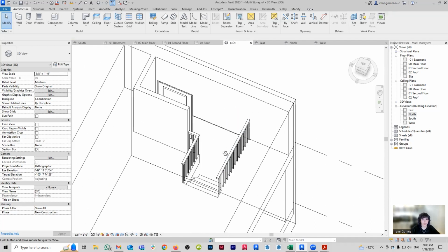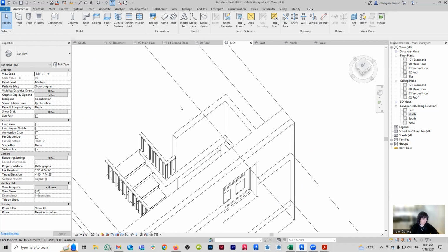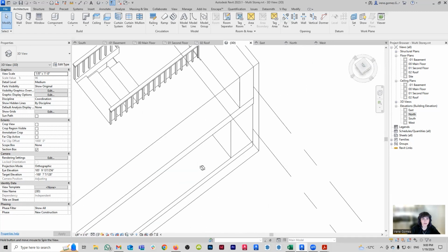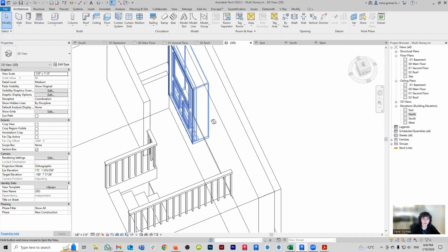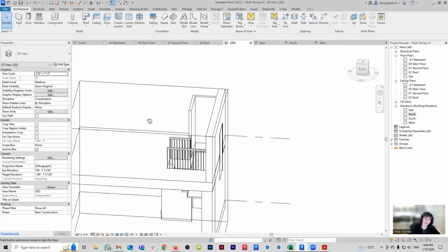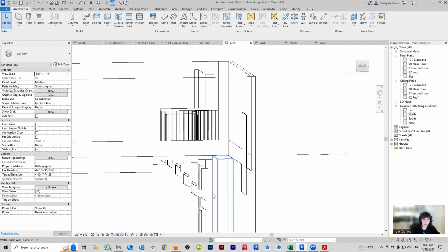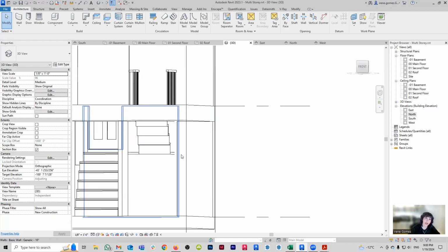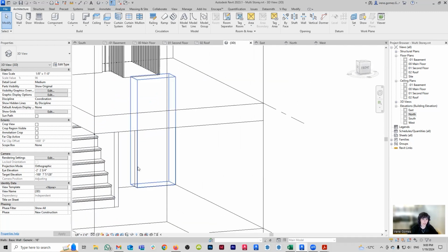Now, by code, this is not enough. You also need railing to be, oops, my alarm. You also need railing to be at the very least right next to here on this wall going to the door, to that landing. Why is this looking... Yeah, no, that's fine. So we need some railing to go here. We should have some wall here. I do not want this open like that because then you're going to have to put some railing. Anyway, I'm getting inside my head.